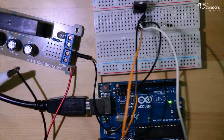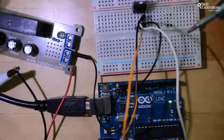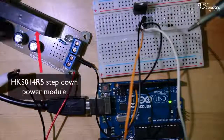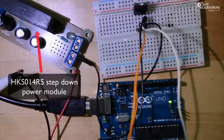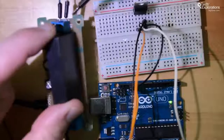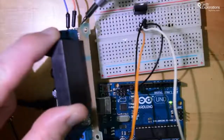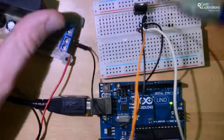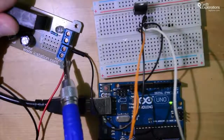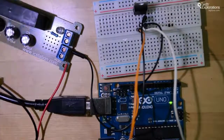So what I've got in this circuit is the Arduino, of course. I've got the TIP122 Darlington here, and I've got a power supply. This power supply is able to take an input that goes up to 30 volts, so whatever external power supply I have available that goes up to 30 volts, I can plug it in here, and on the output it's going to give me 12 volts plus 5 volts regulated voltage.